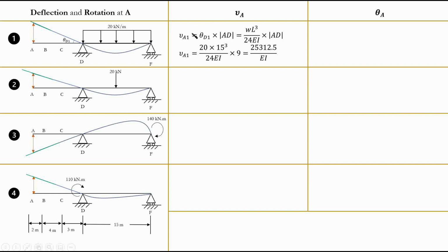The reason is that in our assumption, when we are deriving the equation for this deflection based on elastic beam theory, we were simplifying our equation and saying that our deflections and rotation values are very, very small. Because they are very small, we know from calculus that the tangent function and the linear y equals x function, so y equals tan x and y equals x, are equivalent around 0.